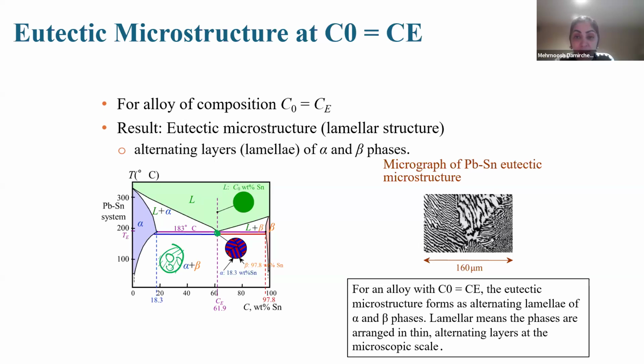This is so fine, uniform microstructures, with enhanced mechanical performance and properties, including strength and toughness. So it is the reason that we as designers and engineers look for the eutectic point, means fix and control the weight percent or composition at this composition, CE, and temperature at this point, for reaching the best microstructures, uniform, and best mechanical performance. Okay.